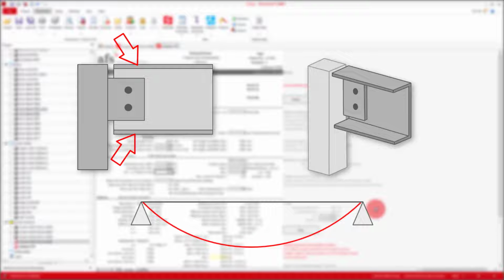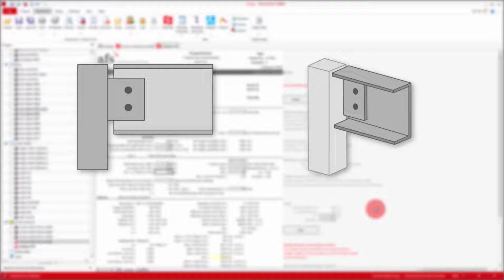This also aligns with the fact that we designed all our members as pinned and supported. Now, although you could go ahead and design each individual connection in a project, for a residential house it is typically more appropriate to provide a fairly uniform set of connections throughout all the framing. This approach will make it a lot clearer during construction and will require less details in the drawings and also less design work. For PFC beams like ours, one approach might be to provide two M20 bolts with a 10mm cleat for all PFC beams to columns or other beams, and increasing it to 3 M20 bolts where the PFC size is 300 or larger.